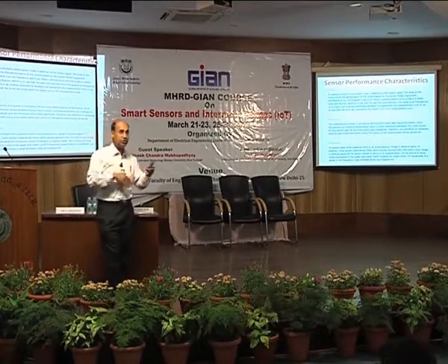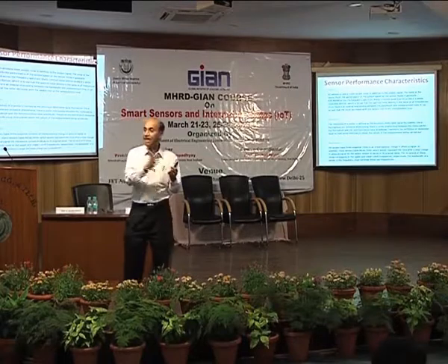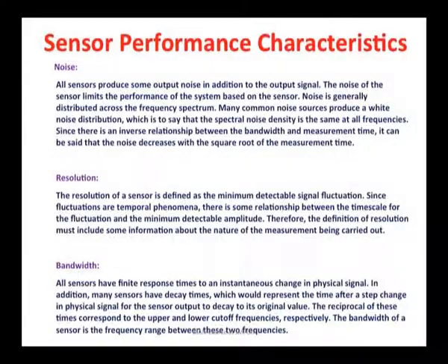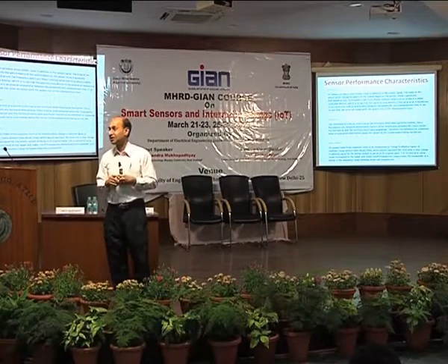Sometimes for the op-amp they also give another value called the gain bandwidth product. Usually an op-amp, you know, amplifies. If you amplify, your bandwidth is reduced, because usually the gain bandwidth product is kind of constant.